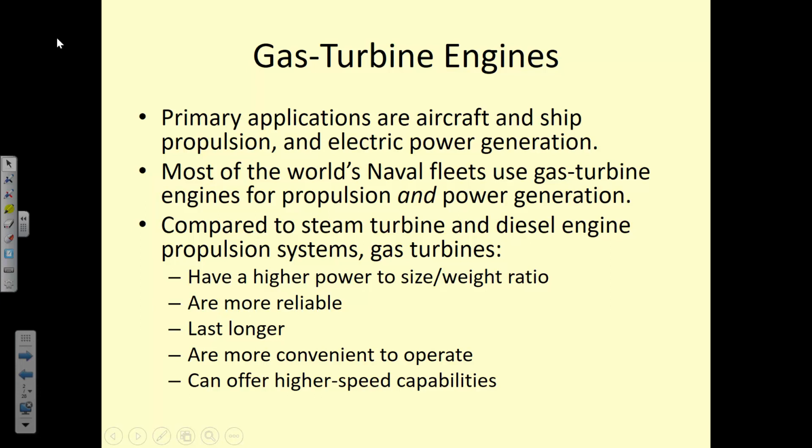So when we're looking at steam turbines versus gas turbines, there are a lot of significant differences. The first one being that a gas turbine is not operating in 2 fluid states. It's always a gas, whereas in a steam turbine you're alternating between a liquid and a vapor. So that's a major difference that makes a gas turbine have a compressor, which in turn requires a lot more work being put into the system in order to keep the system going. And we'll talk about that a little bit later.